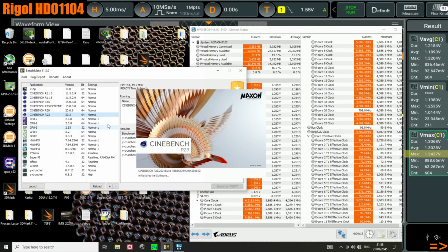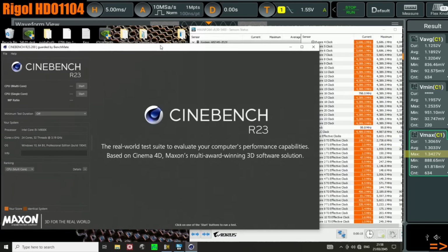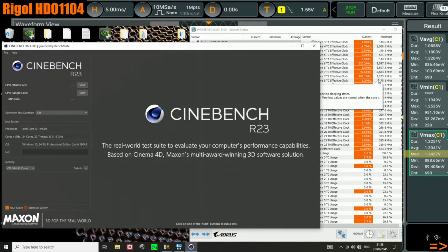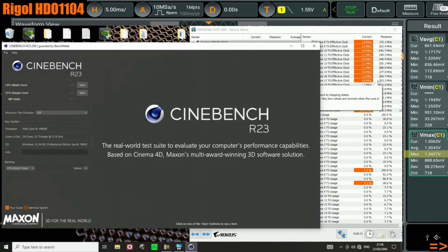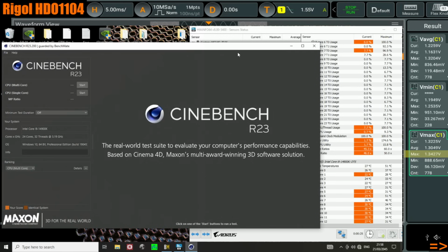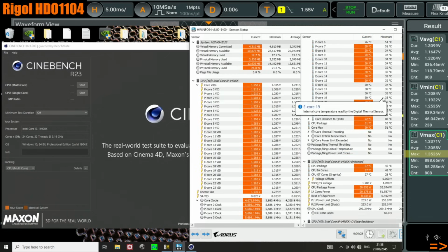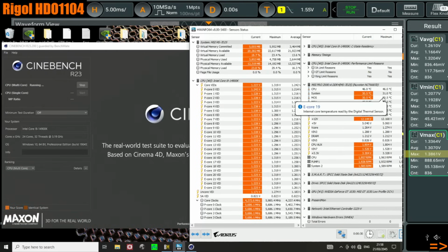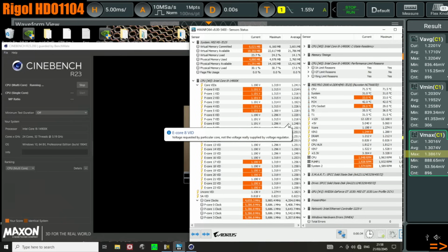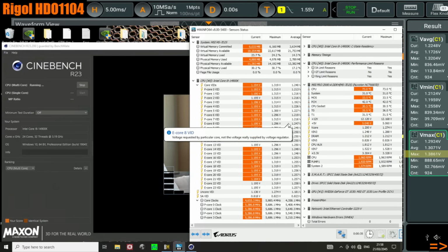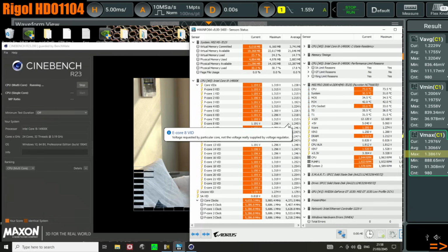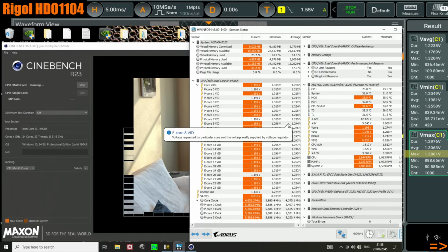Now, the thing with these negative voltage offsets is that Intel CPUs do have some built-in error correction, which means you're not necessarily going to see outright crashing. You can end up seeing weird performance issues, crashing, just weirdness. So if you're undervolting your CPU and your system starts being weird and slow and buggy, you might be undervolted too much.